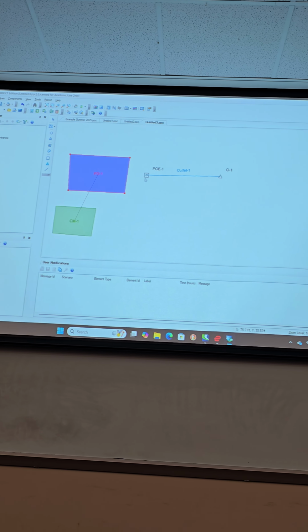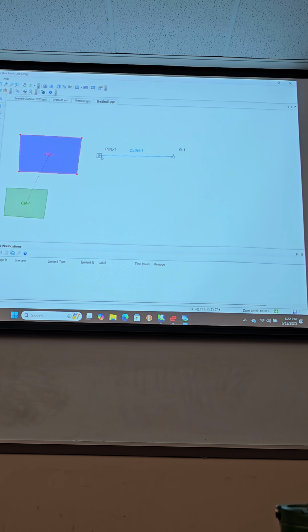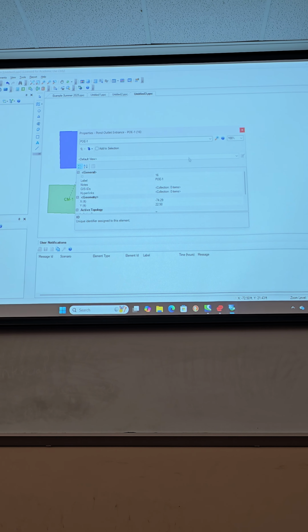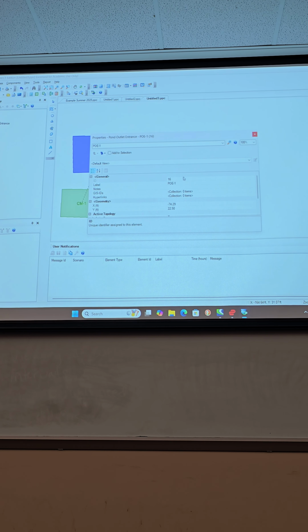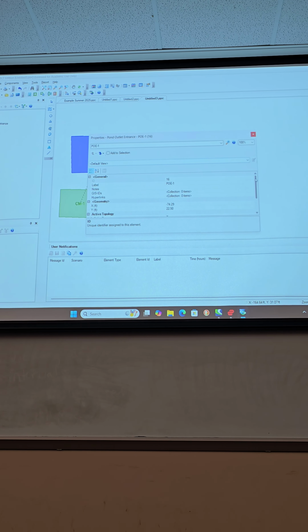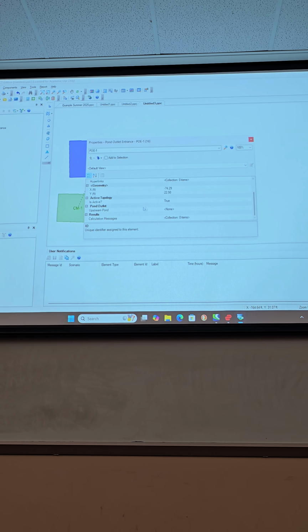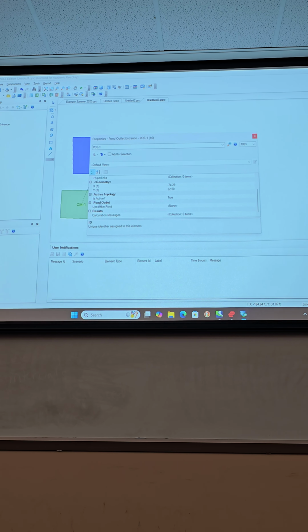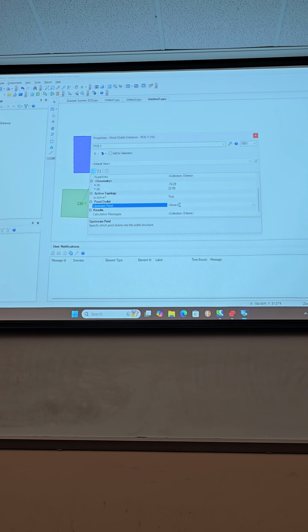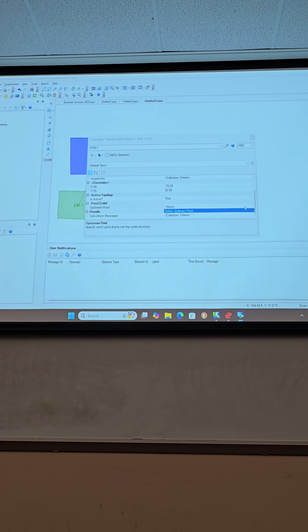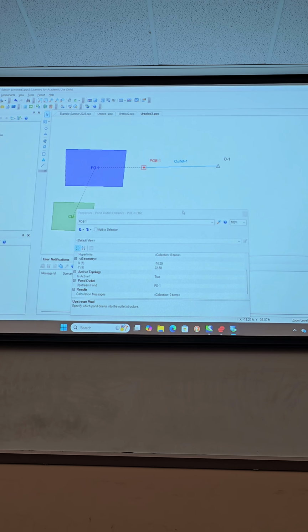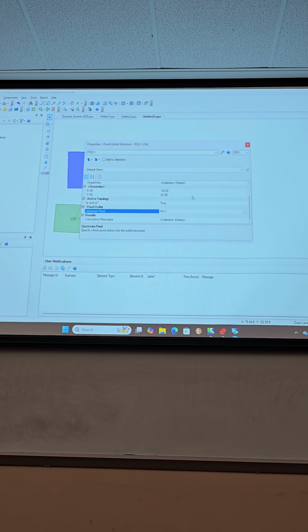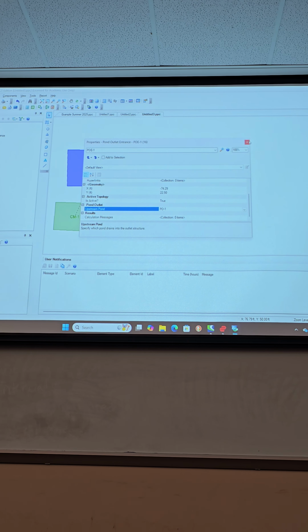Okay, so then if I click on this POE, which is the pond outfall entrance, I need to do a couple things here. The first is under pond outlet, I'm gonna click that, and I'm gonna select the pond, so it can connect it. Actually, that's all we have to do for that one.